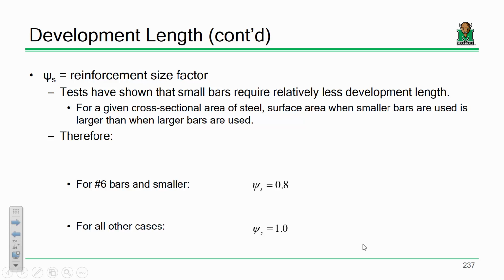Then we figure out what our reinforcement ratio is. Then we figure out what this is, right? Y'all remember that? Now, we have a required area of steel, but how do you figure out what you use? You have an area of steel that's required that's 4.5 square inches. How do you figure out whether you're using 3 number 9s or 4 number 7s or whatnot? How do you figure that out? You've got the spacing in that bar chart, right?